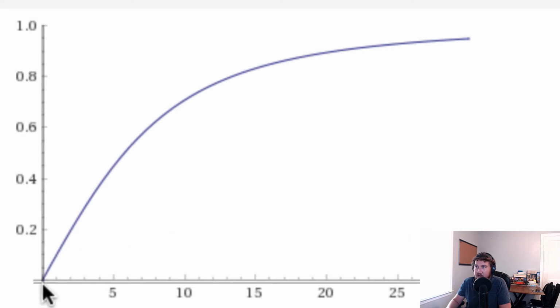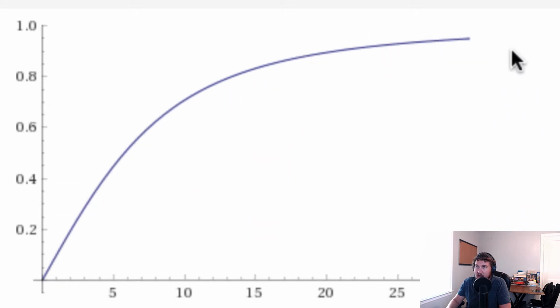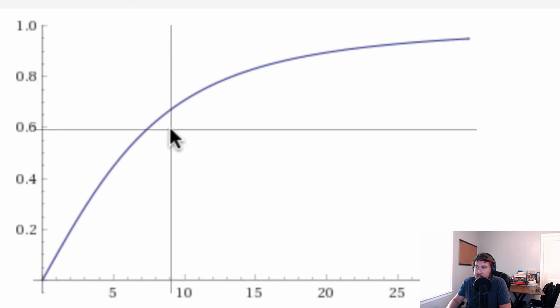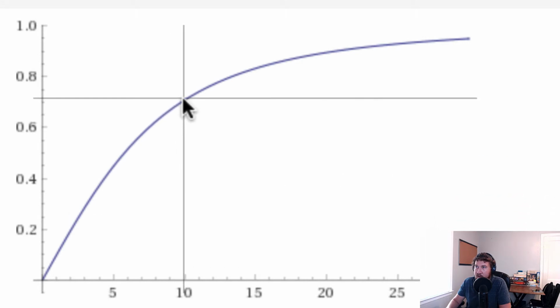Now here you can see where it starts down at 0, or drops down as low as it can, and then rises up. So we're passing the higher frequencies this time. And just like before, our cutoff frequency was at 10. And if we look at where we are on the vertical axis for the transfer function at 10 radians per second, we're back there at 0.7. So this transfer function generates a high-pass filter with a cutoff frequency at 10 radians per second.